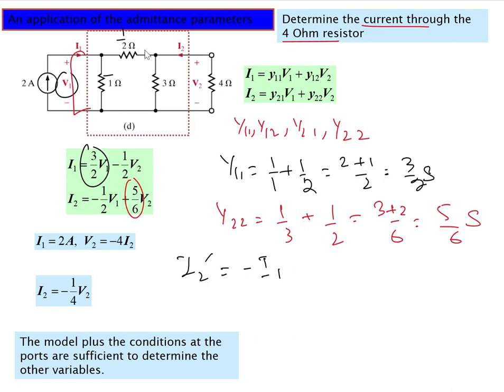So I2 dash is flowing here, which is opposite of I1. I1 is not flowing in it because this is 0, because this is a better path for it. So that can be calculated as the branch current in which the current is not flowing: 3 divided by 3 plus 2 ohm, which is 3 divided by 5. So we have 3 by 5 into I2 here.